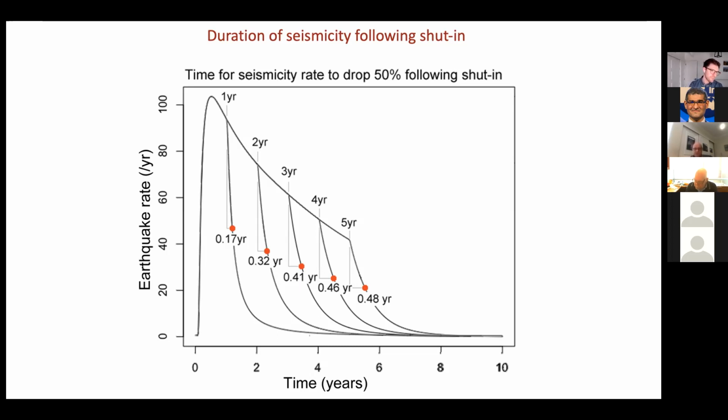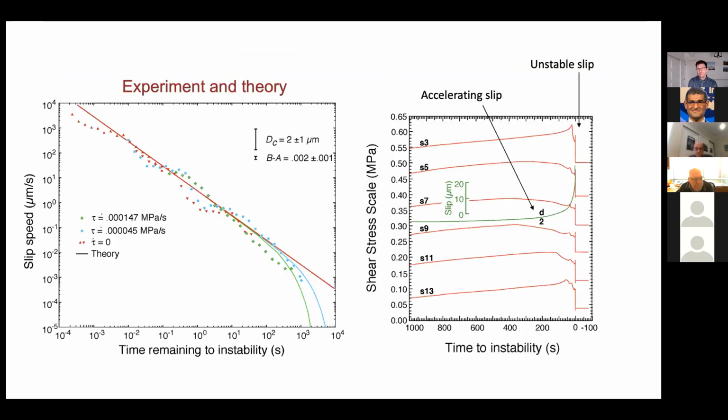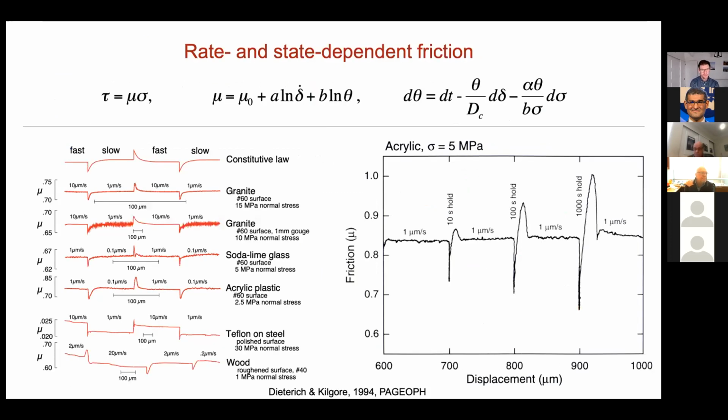I understand. So following with that, another quick one. So you're using a slip rate model, and as you're saying, by scaling up the model, characteristic distance disappears. So how do we know if a slip is stable or unstable? I mean, the stability of a slip depends on the characteristic distance and also the post-peak slope of the stress-slip curve. Yes. Okay.